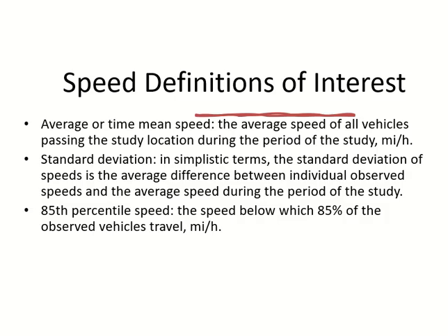Okay, so if I tell you 85th percentile is 30 miles per hour, so 85% of data is under 30 miles per hour. So it gives you an upper limit. The percentile gives an upper limit. So whatever the value is, you can consider the percentage of the data under that limit. Okay, so 85th percentile of the data, and why it is important, we will talk about it.